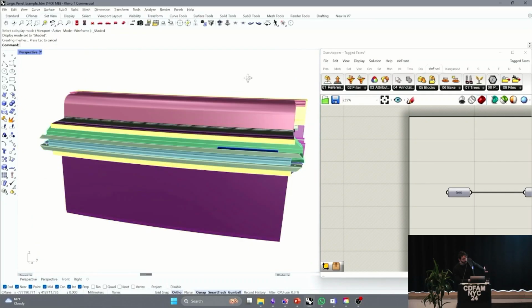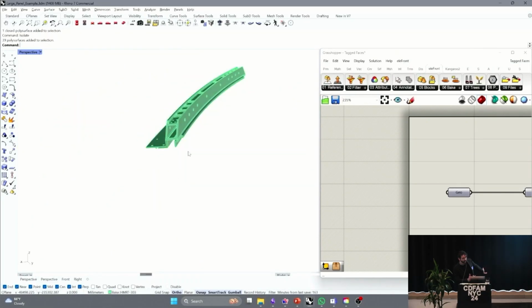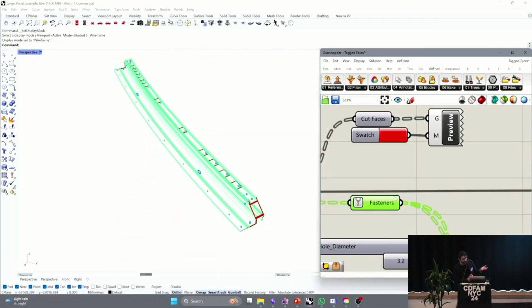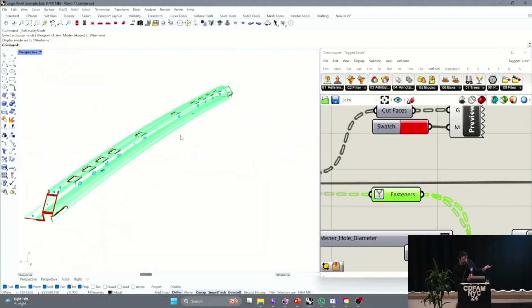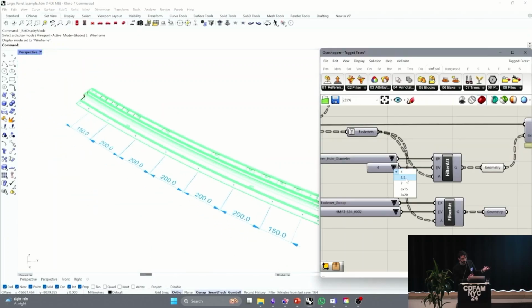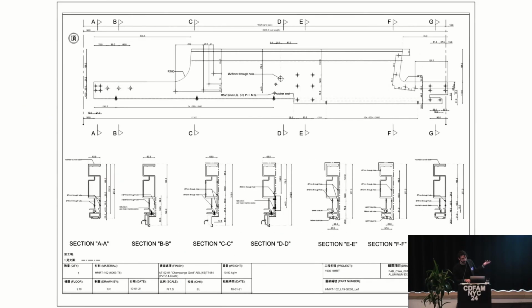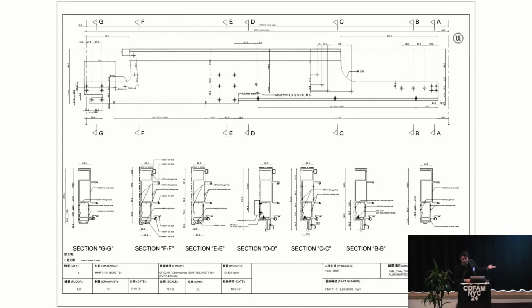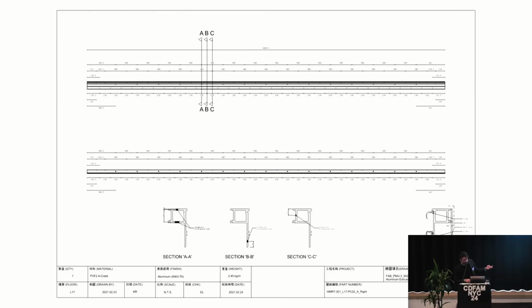Yeah, we're just going to grab one here at random, and then what you'll see is Grasshopper is able to determine which faces are cut with a saw and which faces are drilled with a router bit, and then you can separate them by their hole type, and then you can measure them. And that lets you do things like generate fabrication tickets automatically. So to skip ahead a little bit, we ended up developing 1.5 million fabrication documents for this job.